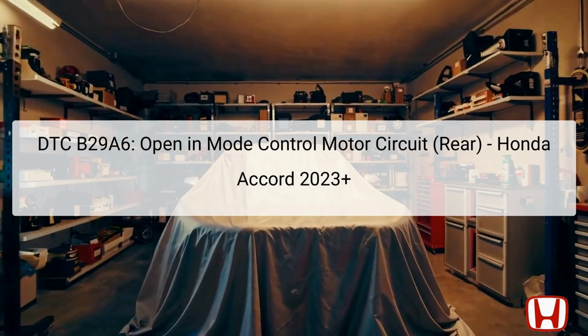The climate control unit monitors the performance of this motor, and if it detects an irregularity in voltage or performance, it triggers the DTC B29A6 to alert the user or technician to investigate further. Overall, this diagnostic trouble code requires careful assessment and troubleshooting to restore proper functionality to the climate system.